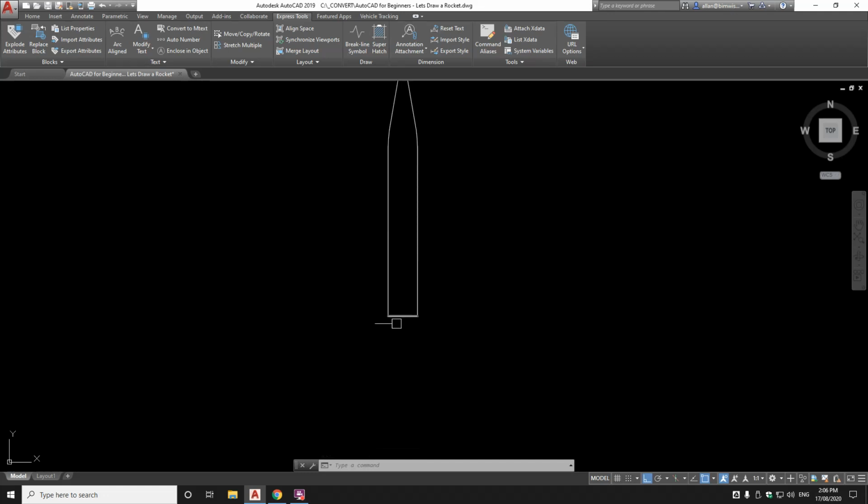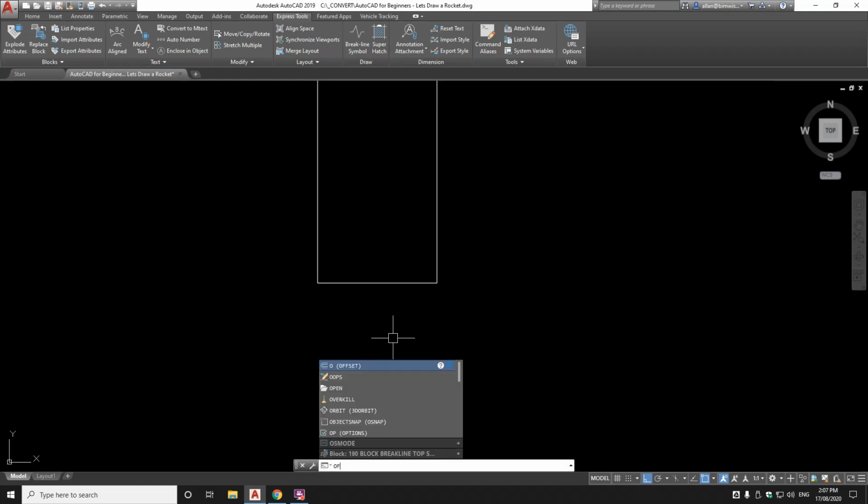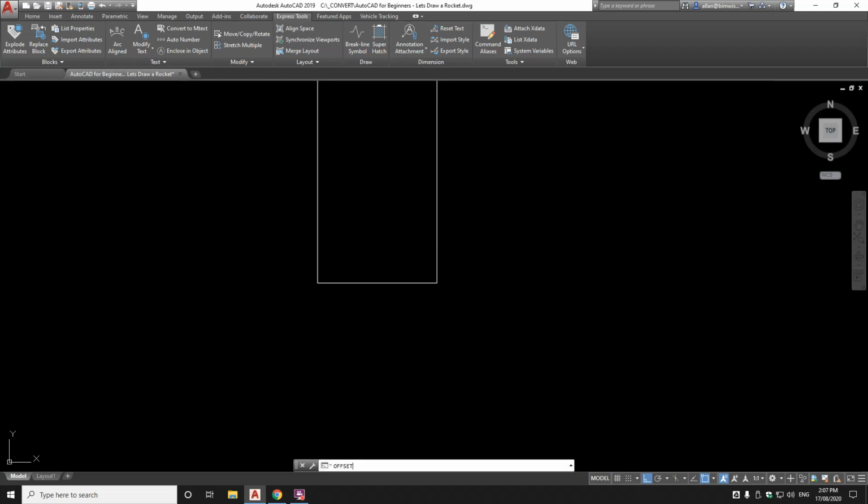Now I've got to have the bell nozzle at the bottom. We won't do a bell, we'll do a trapezoid. And I'll use and introduce a new command here called offset. Now we know that distance across the diameter is 3,700. So let's make our bell a little bit, not the same width, but shorter. And I'll use the offset command to offset that line. O-F-F-S-E-T, offset.